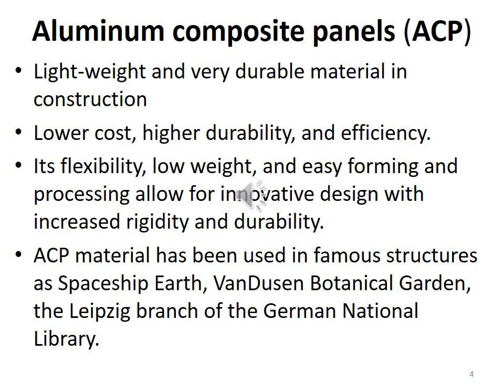However, in some cases, the core material is flammable, and in that case, when the core material is flammable, then its uses must be considered. The standard aluminum composite material core is polyethylene or polyurethane, and these materials don't have very good fire resistant properties unless these materials are treated to make them good fire resistant to be used in aluminum composite material.